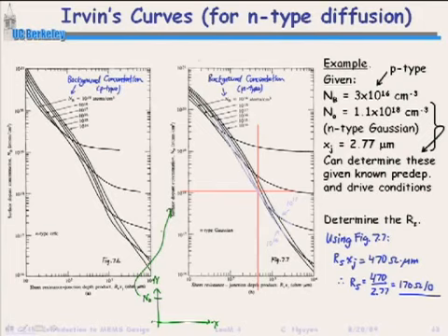Okay? And then you want to know the sheet resistance in the end. And all of these curves are plotted with respect to background concentration. So that's n sub b. So all of these things are there, right? That's background concentration. X of j is in this formula here. And you're usually looking for r sub s. Okay? So you know how to do this, right?